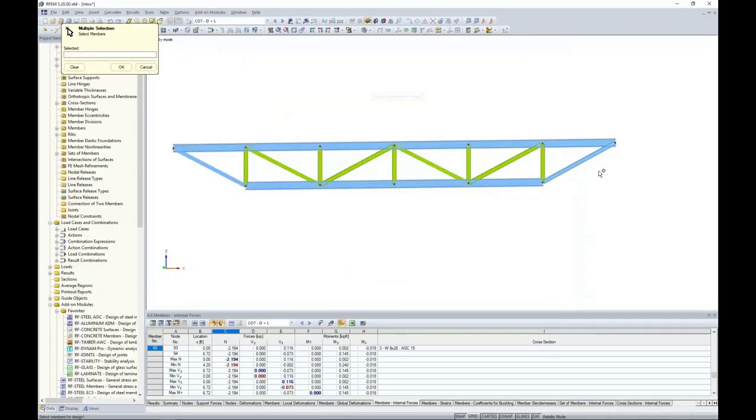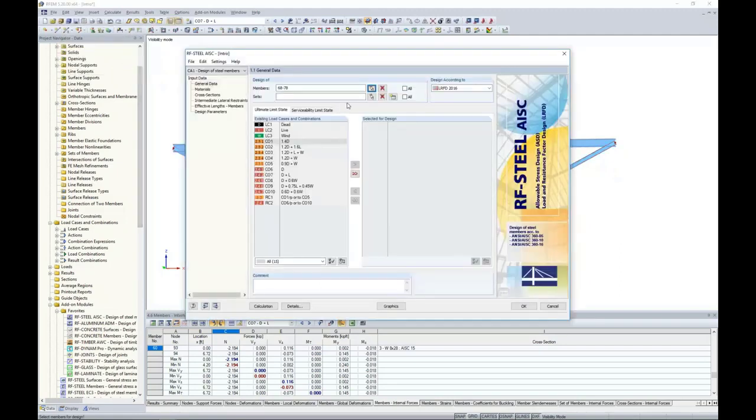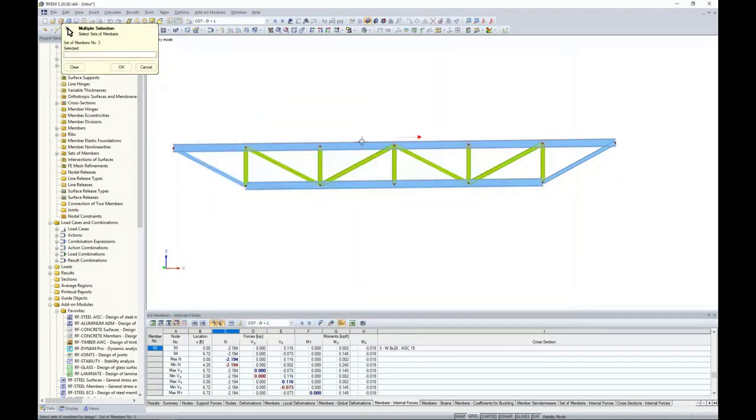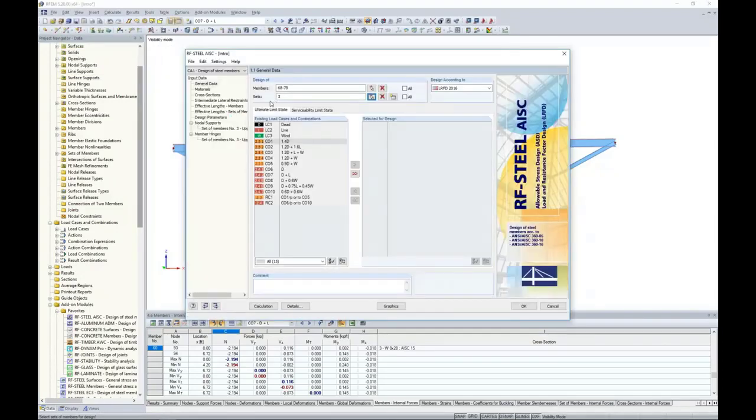And as I mentioned, we want to design these web members here. We'll choose these web members with our dialog box, and I click OK. I do want to design a set of members here. So again, we can design this top cord as one continuous member with what's called sets of members. I choose my LRFD load combinations for ultimate limit state design, and we can check deflections as well. So we move our ASC load combinations under the serviceability limit state design over to the right. Then it's really as easy as just moving down this list.